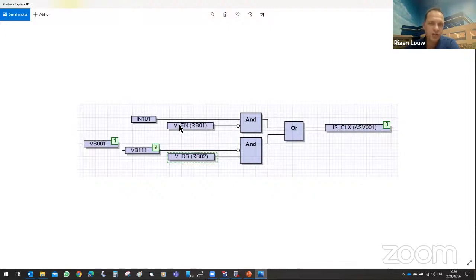So if you have virtual logic enabled, the negated function here will completely block the hardwired signals going into this status. Whereas if I have now the virtual logic enabled, this should actually be negated here as well. My bad. I quickly drew this up this morning just to give you guys an illustration. But what I would have here is the virtual signal and the quality signal, as well as that enabled signal here. That description is not right. But then I would have this logic enabled and that disabled. And when I switch back to the hardwire signal, I would just simply disable the virtual logic, and then I would be completely and solely relying on the hardwire signals coming into the relay.